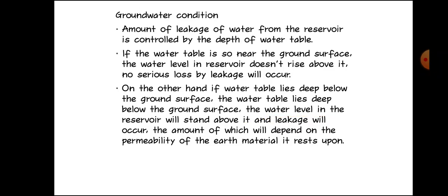Groundwater condition. The amount of leakage of water from the reservoir is controlled by the depth of the water table. If the water table is so near the ground surface that the water level in the reservoir doesn't rise above it, no serious loss by leakage will occur.